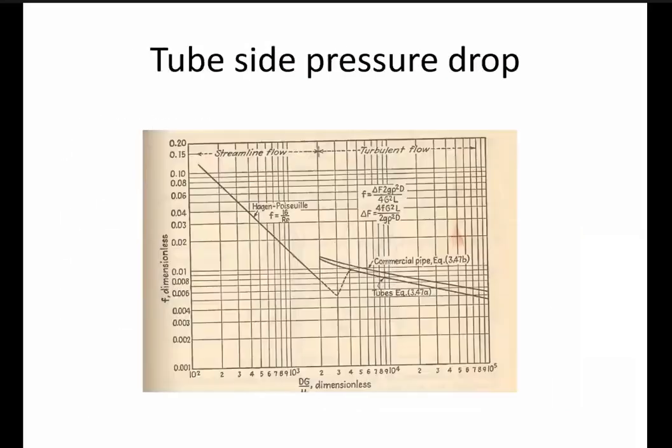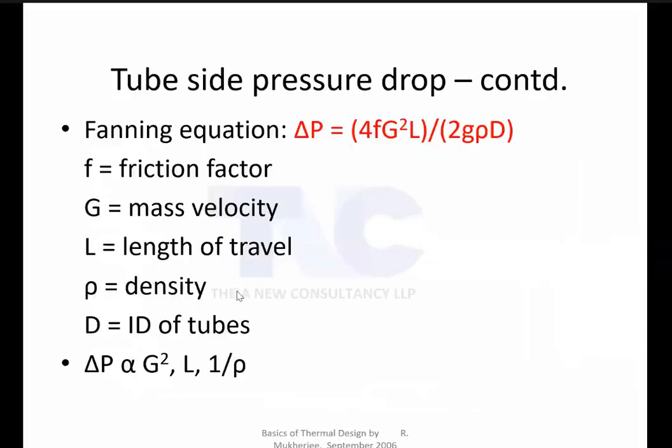Another important thing I want to discuss is your pressure drop. Remember, pressure drop is directly proportional to your mass velocity. Pressure drop is directly proportional to your length, right? More the length, more the pressure drop. Pressure drop is inversely proportional to your density. That is why gas will have less pressure drop, liquid has more pressure drop. So I hope you remember this fundamental concept.